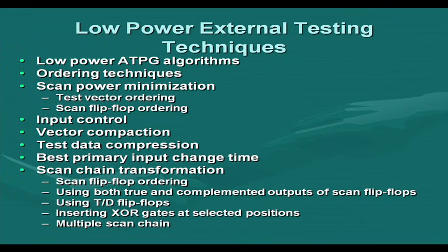Now, there can be several techniques by which we can do this external testing in a low power manner. So, we can have some ATPG algorithms that target low power. It will try to generate test patterns so that power consumption is less. Then there are some ordering techniques. So, we can change the order of the test patterns to be applied to reduce the circuit transitions.